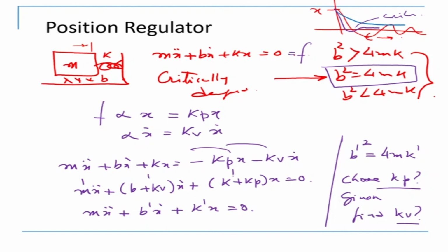The other kind of controller that we look at is what we call control law partitioning, and we try to reduce the system to that of a unit mass. So how does this work? We try to have a model based portion and a servo portion. We try to divide the controller in two parts: a model based portion and a servo portion.